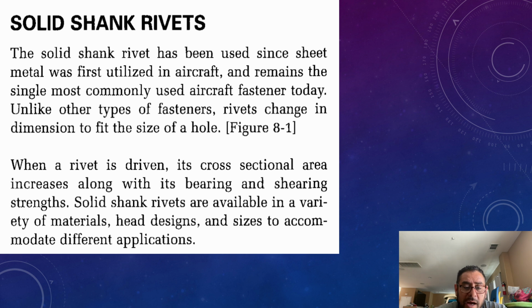And also, when you're working with rivets, it's easy to lose track of them, so it's important that you account for all your hardware when you're working on an aircraft.